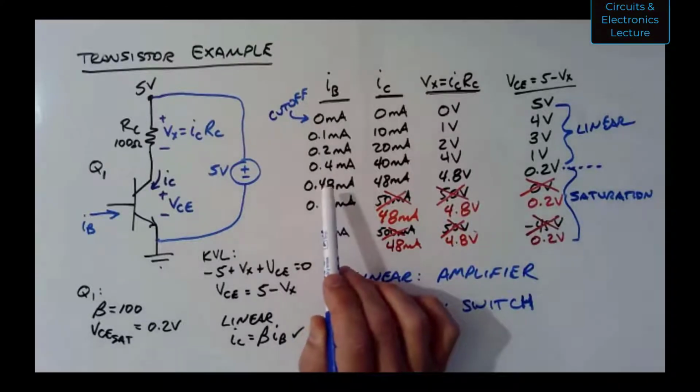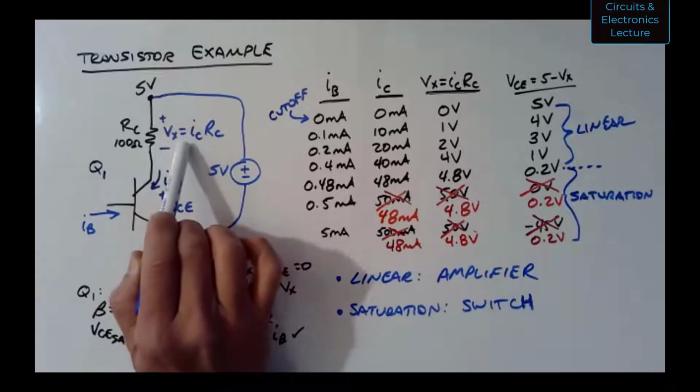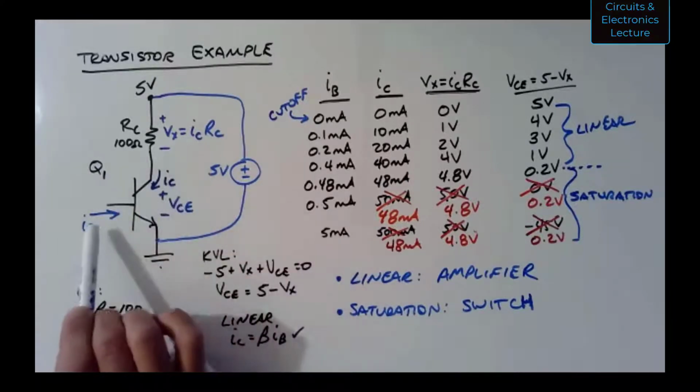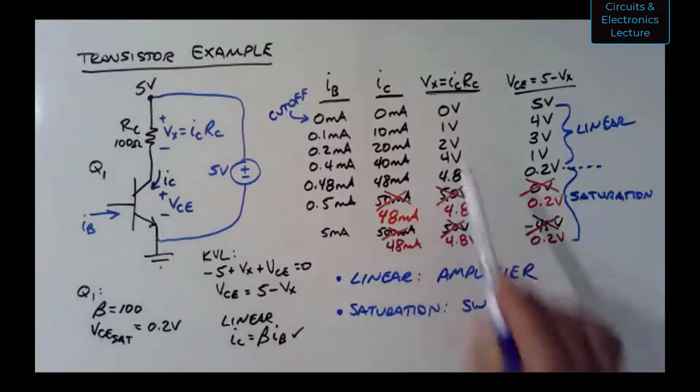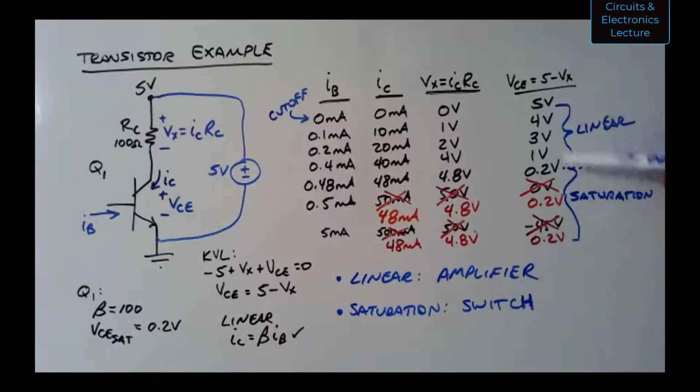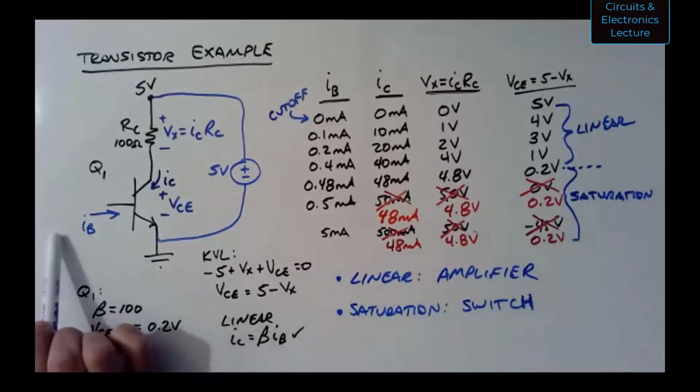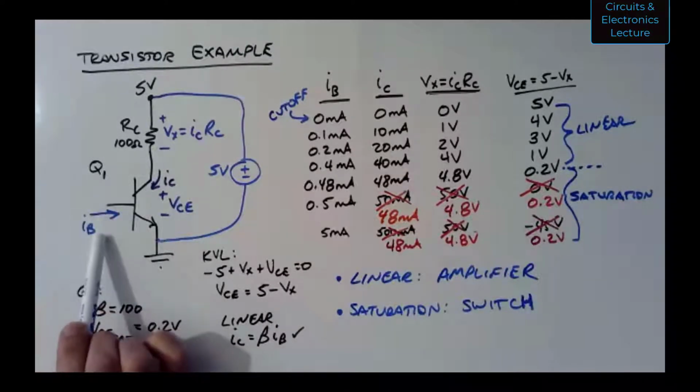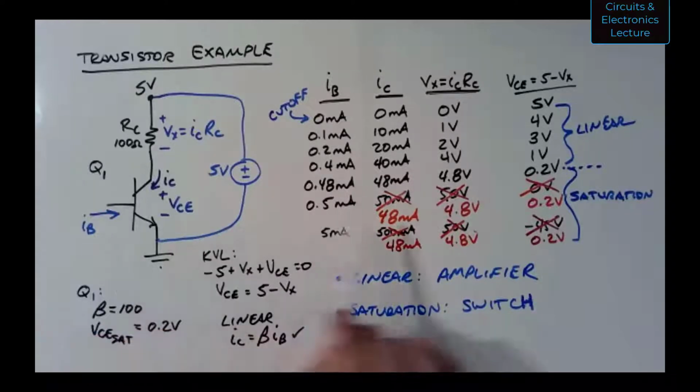So that's what I meant by you have some voltage in a circuit that is controlled by some other variable, like some other current. So this would be a current-controlled voltage source. You've got another voltage that varies in a different way with current over here. So you could use this current IB to control VCE. You could also think of putting a voltage source out to the left through a resistor to control that current IB. And so you could have a voltage-controlled current source or a voltage-controlled voltage source. So all 4 of those controlled sources could be built using just one transistor and one resistor.